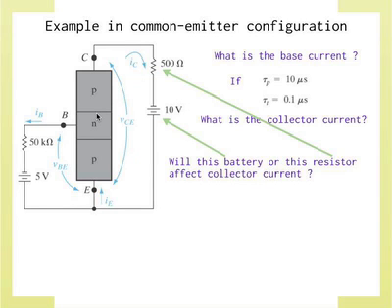There are two PN junctions here, and we know PN junctions very well. This PN junction should be reverse biased, right? Remember, if it becomes forward biased, then it doesn't operate like a transistor anymore. We'll look at that in a second. So this must be reverse biased. So of course, this potential plays a role in that. We don't know exactly what yet. But one can imagine, right? This is connected to that, so it must play some role in reverse biasing it. So I cannot put an arbitrarily large negative voltage there, for instance. I will probably forward bias that junction.